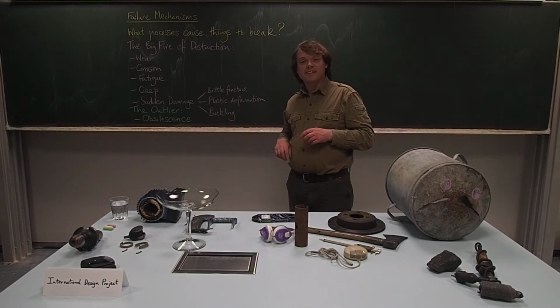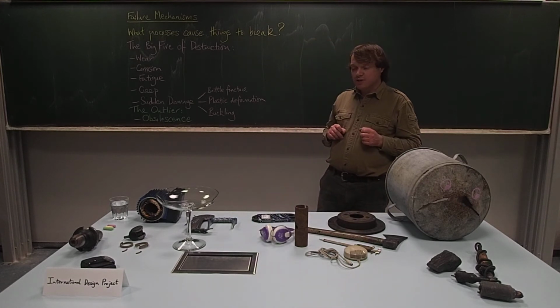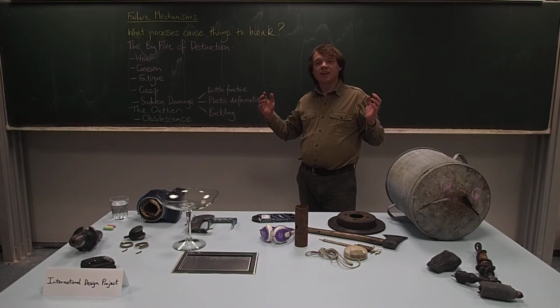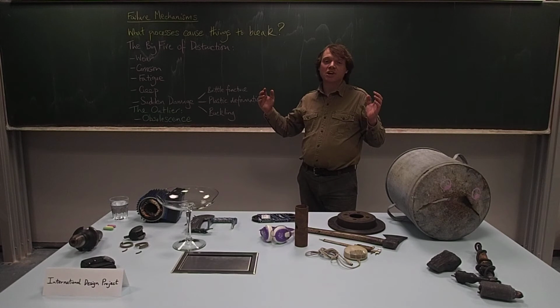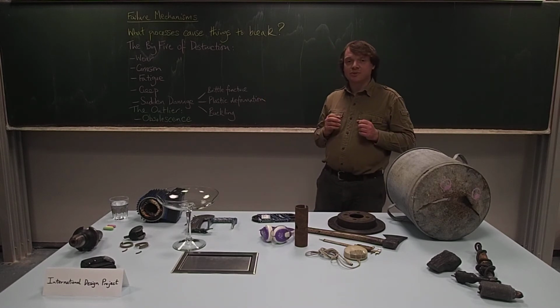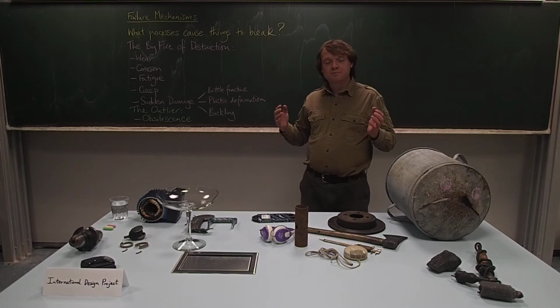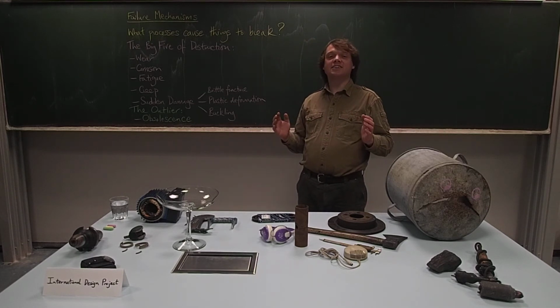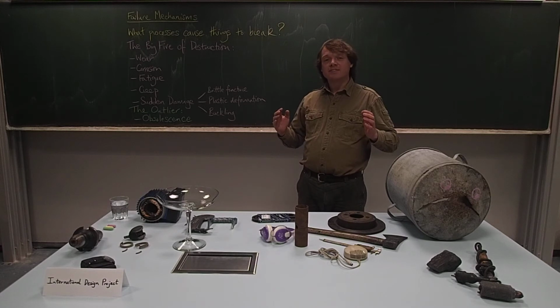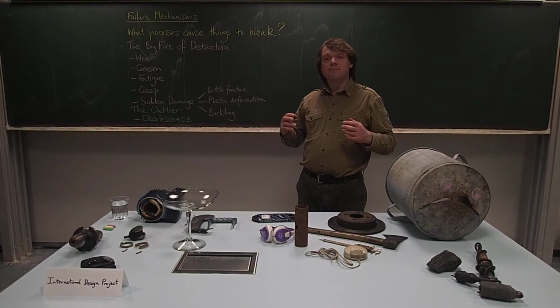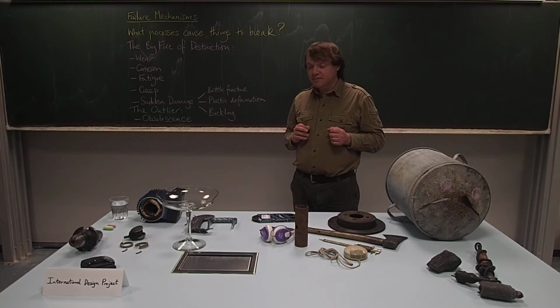The fourth mechanism I'll mention is creep. Now, creep means that you have a load on a component and gradually, over a very long time, it changes shape. Closely related to creep, you have relaxation, which means that you have a deformed component held in a certain geometry, and over time the stress relaxes, so you have less stress in the material, and that then becomes the default shape of the material.